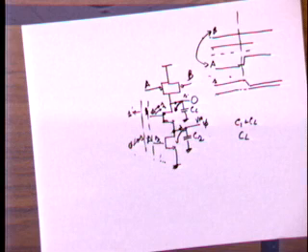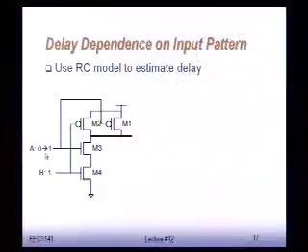And so this has important design implications, because you can imagine if your critical path goes through this gate, you want it to go through one of the inputs of this gate, you want that input to be the top one and not the bottom one. I will go back to this again in a little bit.